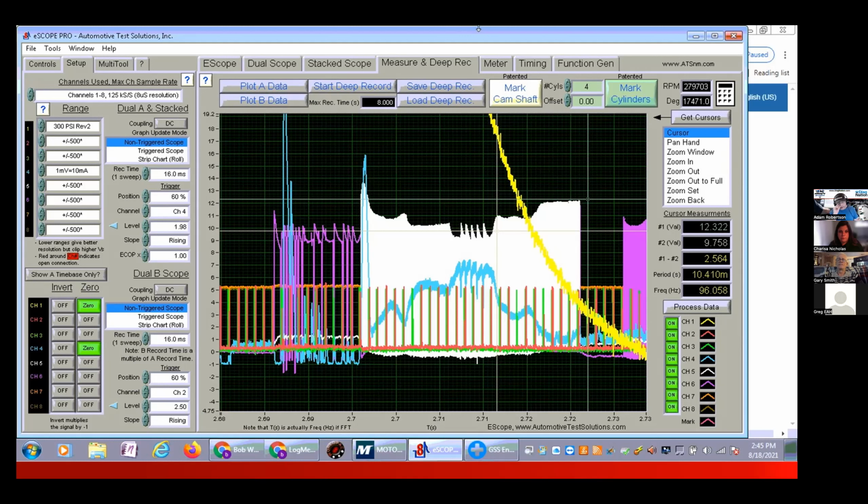What they may have just told us, guys, is this: hey, my APP, and I'll just use an accelerator pedal as an example, because they leave you stranded when they go wrong. So here you've got a car that may have simply said, wow, I commanded my motor to move X amount. I didn't receive feedback from my throttle position. His only diagnostic code strategy may just be able to say, hey, I commanded it, but I didn't see it. My TPS1 didn't equal my TPS2. I didn't get the response I wanted.